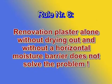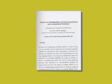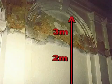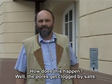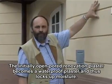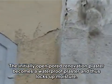Rule number 6. Renovation plaster alone, without drying out and without a horizontal moisture barrier, does not solve the problem. On the contrary, as building research as well as building practice have proven, moisture rises even higher and destroys the old plaster lying above. How does this happen? Well, the pores get clogged by salts. The initially open-pored renovation plaster becomes a waterproof plaster and thus locks up moisture.